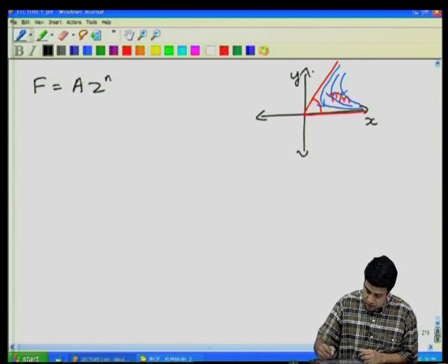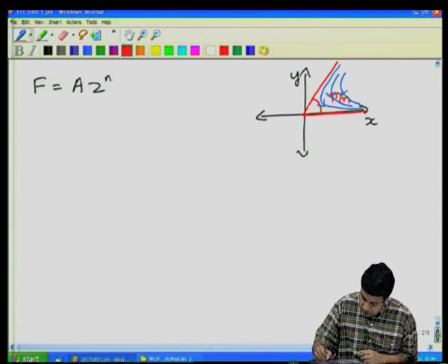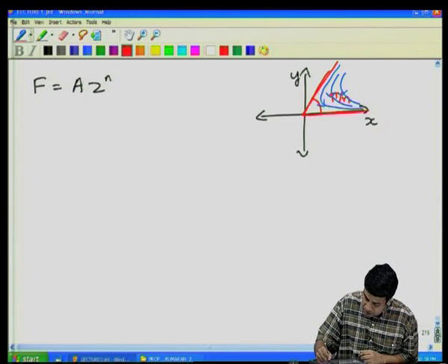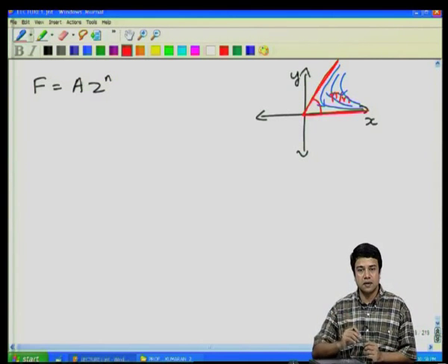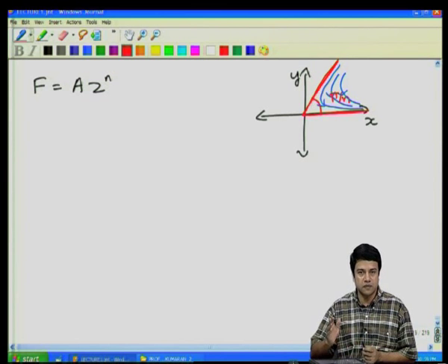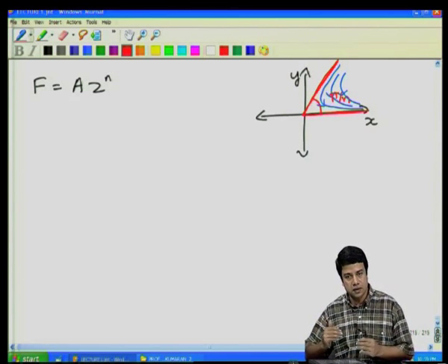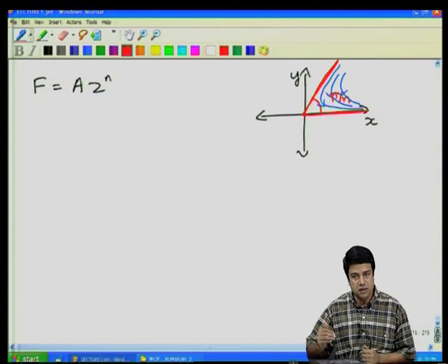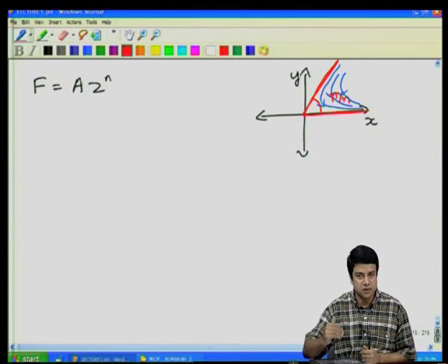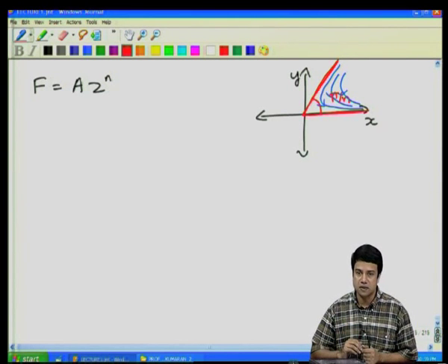Note that the two sides, the two walls of the corner, are locations at which the normal velocity is equal to 0. Okay. So I require for my potential flow boundary conditions that the normal velocity has to be 0 at the bounding surfaces. Since the normal velocity is 0 at these two surfaces, these act as bounding surfaces for the potential flow. Recall, we cannot satisfy tangential velocity boundary conditions at surfaces in potential flow. Therefore, the tangential velocity is non-zero at these surfaces.